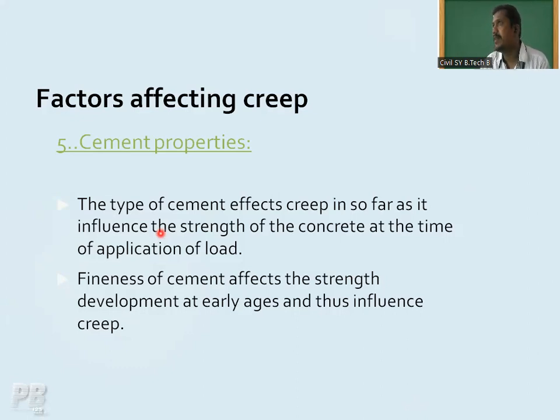You should use the finer cement because it will provide you more surface area, which leads to the proper bonding between the cement and the rest of the particles, and which will improve the strength automatically. Okay, that is why we should use the finer cement as per our design, as per our Indian standard, or which has been mentioned in our Indian standard.